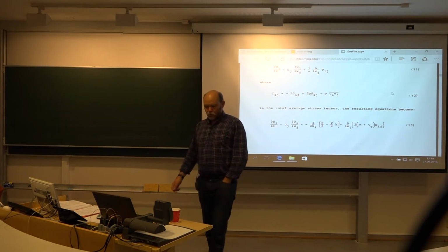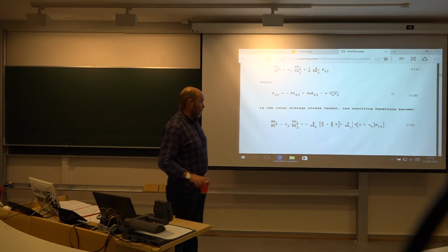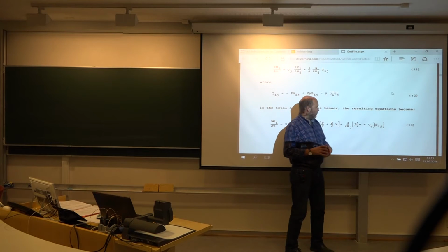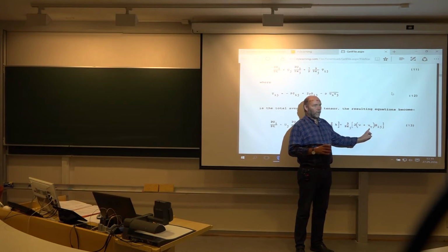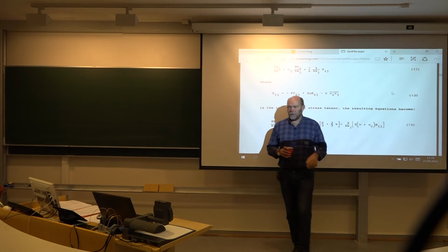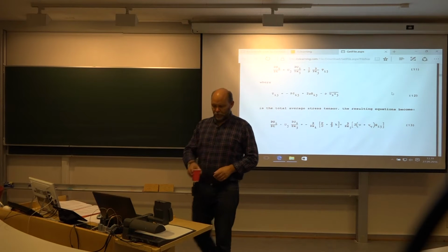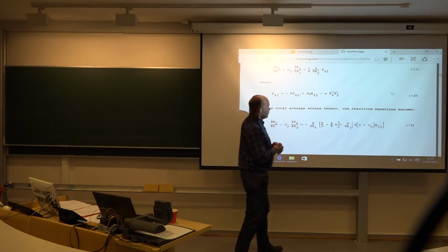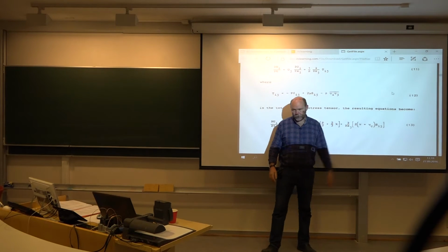And one turbulence model is called Spalart-Allmaras. It's just based on one function, one unknown function. So you have one separate transport equation for this quantity alone. That is one turbulence model that we are going to look into. Very simple indeed. Just one single unknown function.